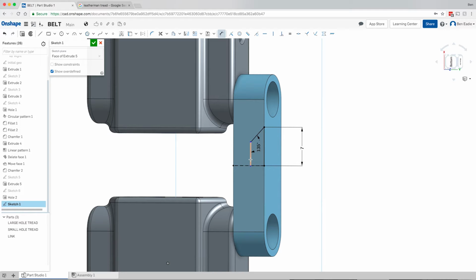And then remember, I want to have everything nice and black. I also want the web of these things to be about 3 millimeters, being the minimum. But this isn't going to cut out everything I need. So what we're going to do is use the mirror. As soon as you select on it, it says select a mirror line. So we're going to select on this guy here.